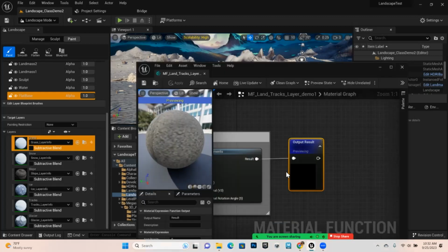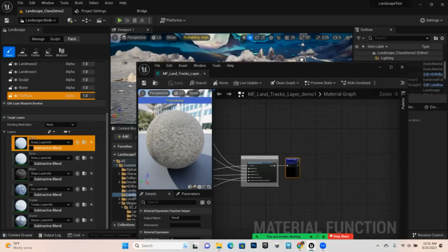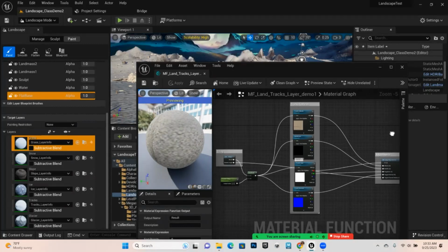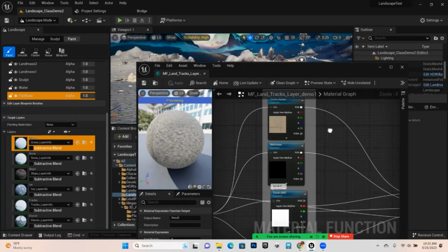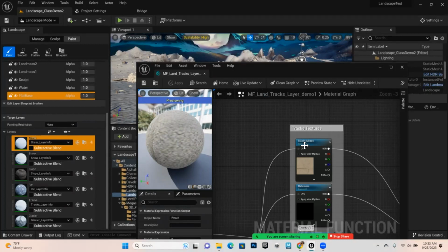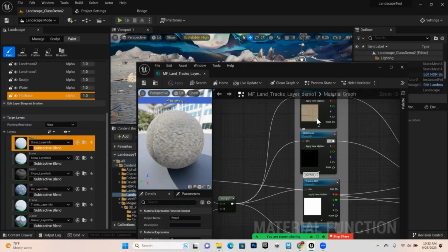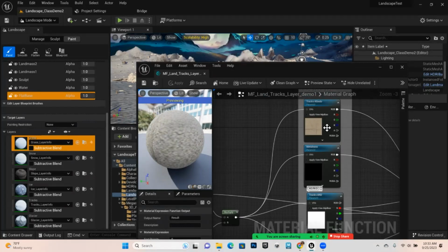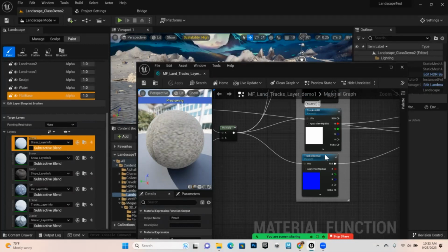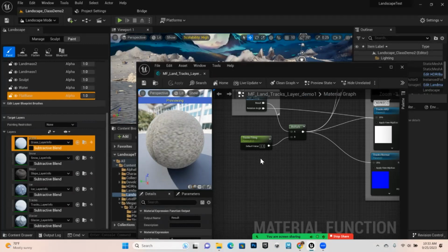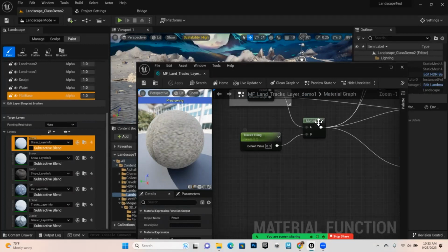last time to create a couple more and label them accordingly. So if I open one of those, that's the one that has the master material in it that we just had to go in and change names on. So in this case, it's for the tracks in the snow. And I added tracks to the names of my albedo and my other ARD, which is roughness and the normal map, as well as my tiling, which I set up last time with the scalar node going into a multiply node.